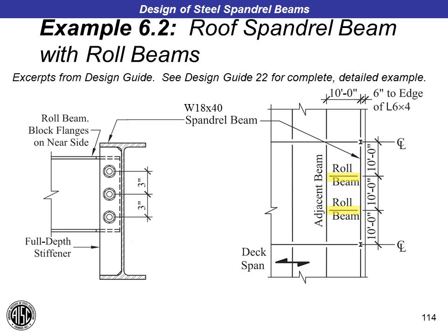But by minimizing the torsional span by providing roll beams, you can minimize the amount of twist that you have to take out of the column. I suppose you could add another roll beam or kicker relatively close to the column to try to minimize that force.